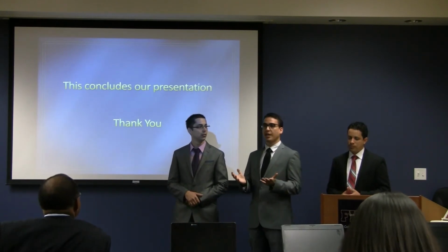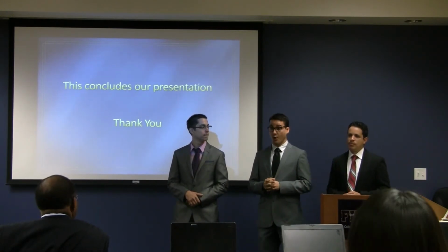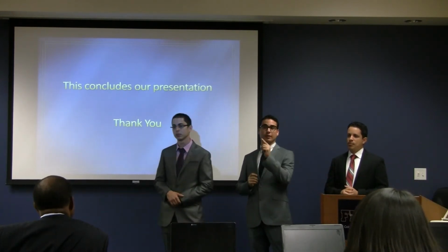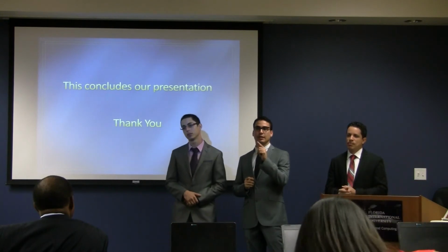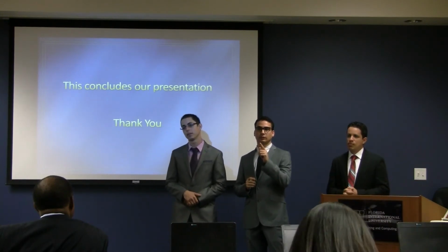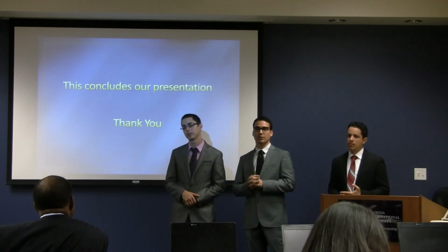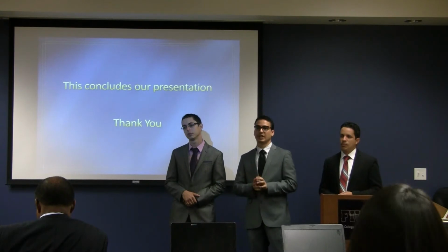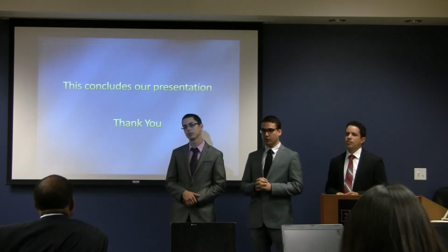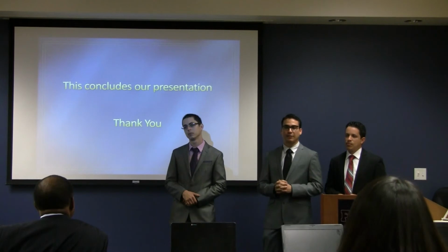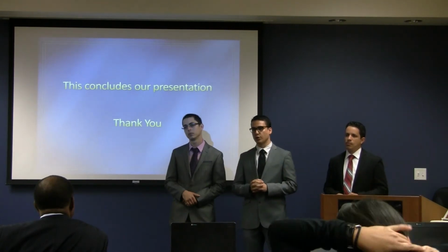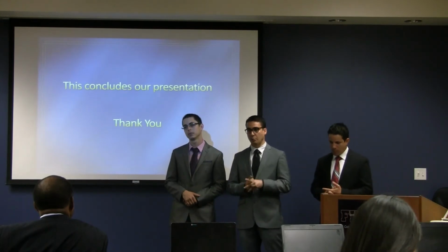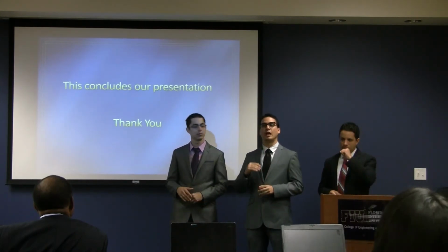The thing is, we were limited by our wind tunnel. But this is your fluid model. You could have calibrated your fluid model with the wind tunnel speed, but demonstrated or presented to us a condition that proved that the high-speed condition would have been the same. At those velocities, we're probably going to need a different model than the one we used, K epsilon two equation, realizable, and non-equilibrium wall functions. At those velocities, we're probably going to need to go a little bit deeper.